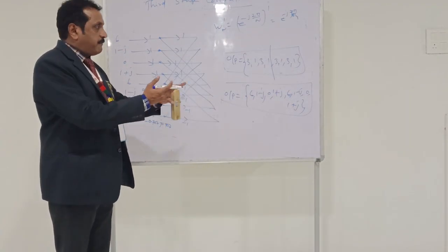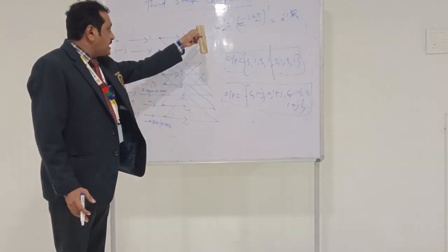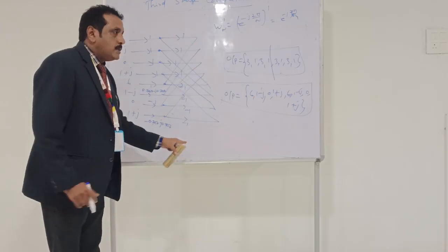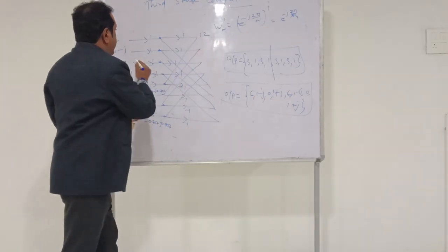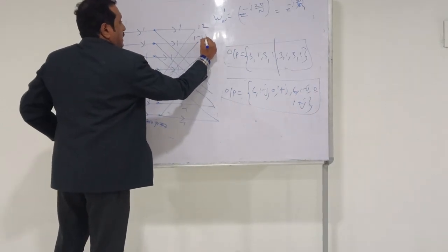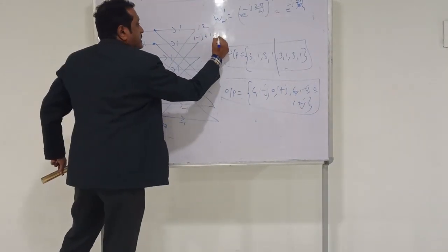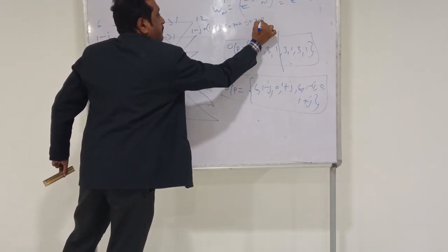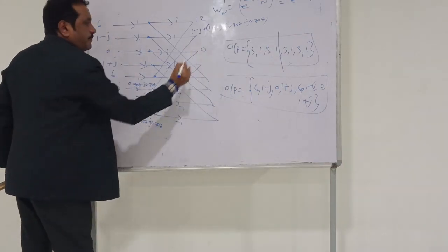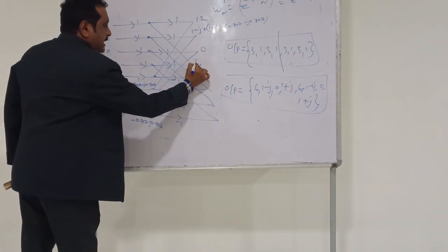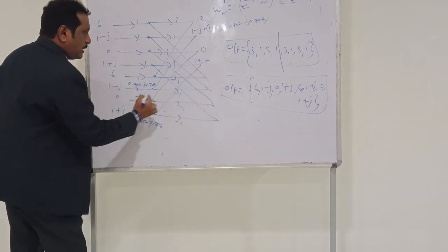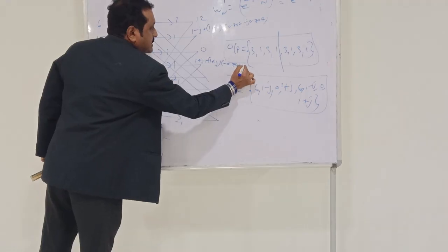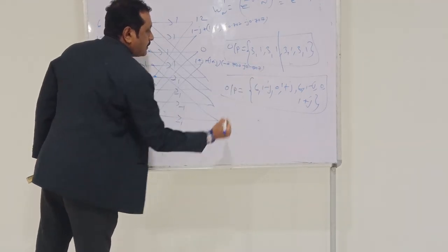Now, whatever we followed in stage 1 and stage 2, the same thing we can follow in stage 3. You can compute the output of each node. The first node is again 12. The second is 1 minus j plus the other one from here, 1 minus j into 0.707 minus j 0.707. The third one is 0, and the fourth is 1 plus j plus 1 plus j into minus 0.707 minus j 0.707.